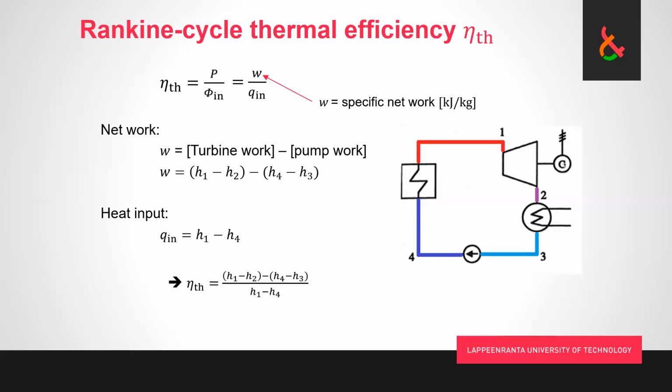An important thing to remember is that we are talking specifically about the heat input to the work fluid. So for example, if we're talking about actual power plants, it's not the fuel input to the boiler, because only part of that we can get into the work fluid. And with those components, we're talking about the work that the fluid does in the turbine, or the work that the pump does into the fluid.